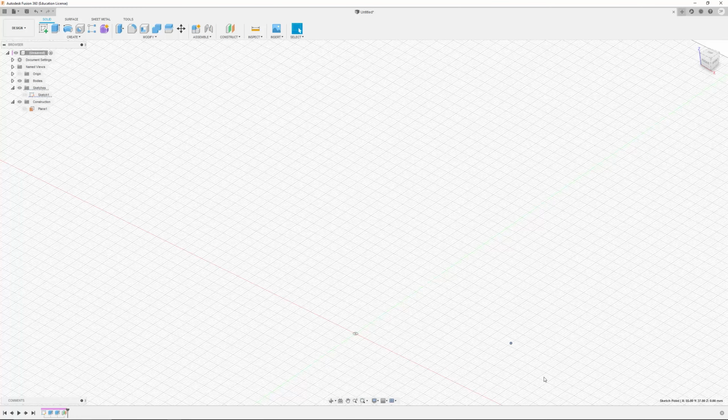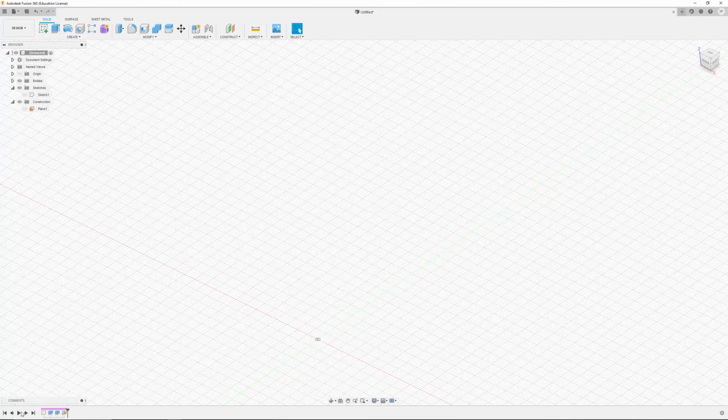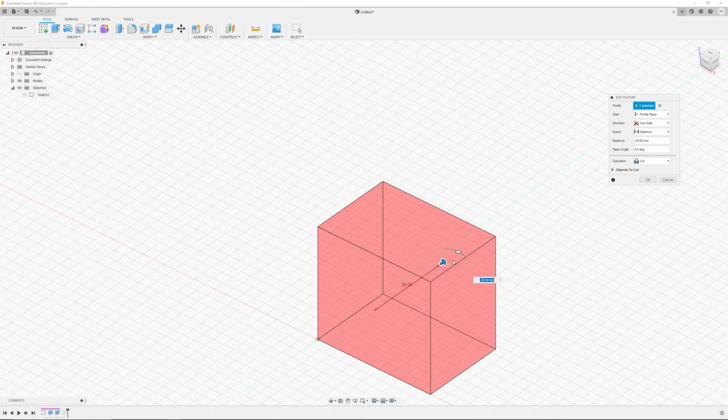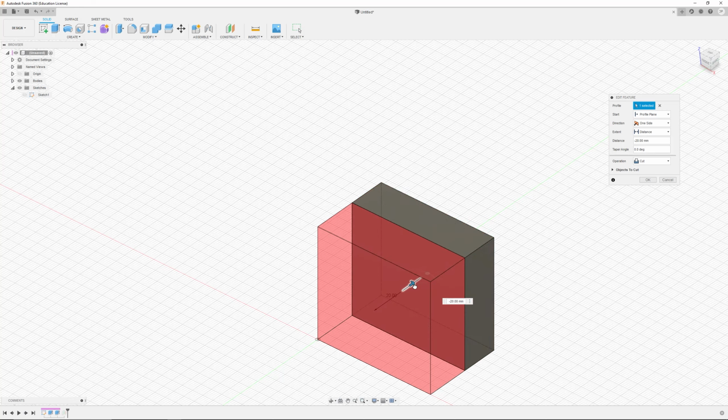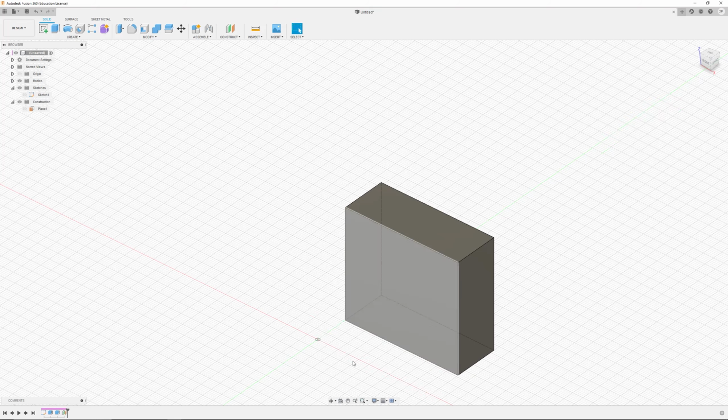And in this case, I believe I've done something where, yeah, I made my initial sketch smaller than my feature down the line there. So it actually completely eradicated it. So I'll have to come back and adjust this one, and then that will make that update. So that's something also to note, is what you do in the past affects the future.